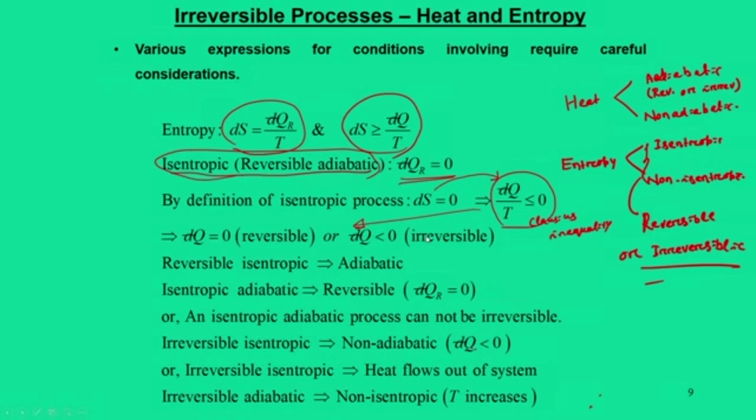True, because this can be written in terms of PdV and TdS, where V stands for the volume. This relation is a point function relation even though it involves work and heat. So the differentials of work and heat are replaced with terms of internal energy. This is another significant property of entropy. We conclude, and now we will try to solve problems on what we call entropy calculations.